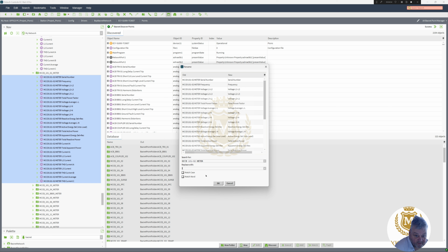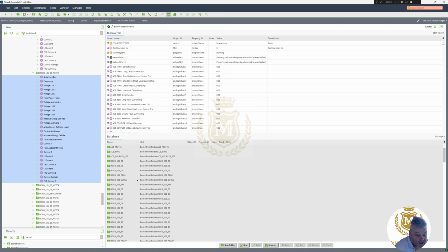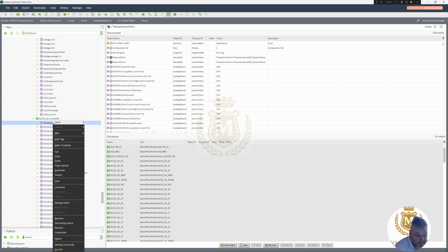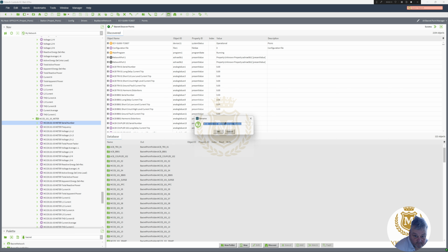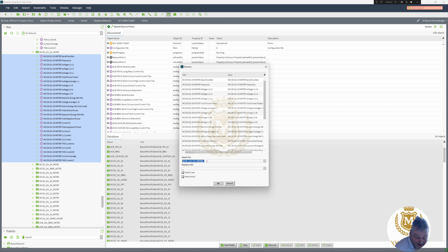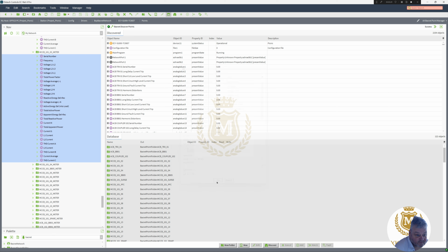And that would be to install a Modbus to IP module, bring all the meters in and bring them straight into the supervisor rather than bringing them into a controller. And it would cut out all this tedious work of writing the software in the controller, naming every point differently, to then bring back to the supervisor. Let me just show you what I mean.